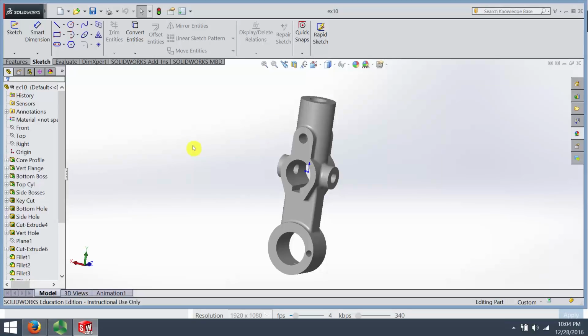And then also, if you're going to make changes, the changes will be tied together from component to component. So if you change the hole location of something or the diameter, whatever has been built in context will move and adapt with it. So I know that's a lot of verbiage, but I just wanted to get that out there. And then again, like I do with all my demos, I'm going to keep this really simple and basic. Just going to add 2 or 3 parts to this to give you the idea. So okay, let's go.